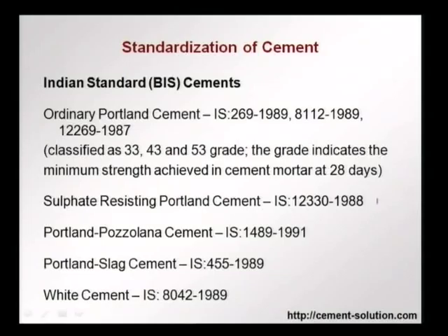We also have some special cements such as sulphate resisting Portland cement, where we have cement that should be used where you have very high sulphates in water or in the soil.